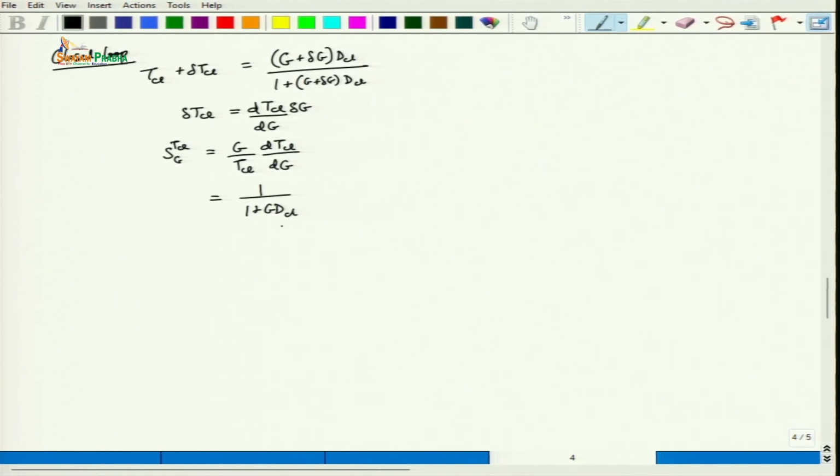So here you can see what's the difference from the open loop system: this sensitivity depends on your controller, which you can design. So say for the first one, A, this sensitivity is 0.01 and the second one is 0.001, then obviously with regards to the sensitivity, I will select controller B because it has a lower sensitivity.